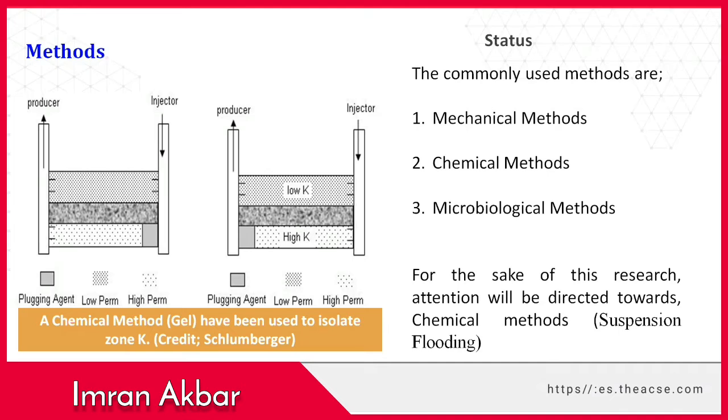So our main purpose is to displace the oil from the reservoir, especially from the low permeability layer, which is a difficult task, and we are doing this task with the help of suspension flooding to displace the oil from low permeability layers.